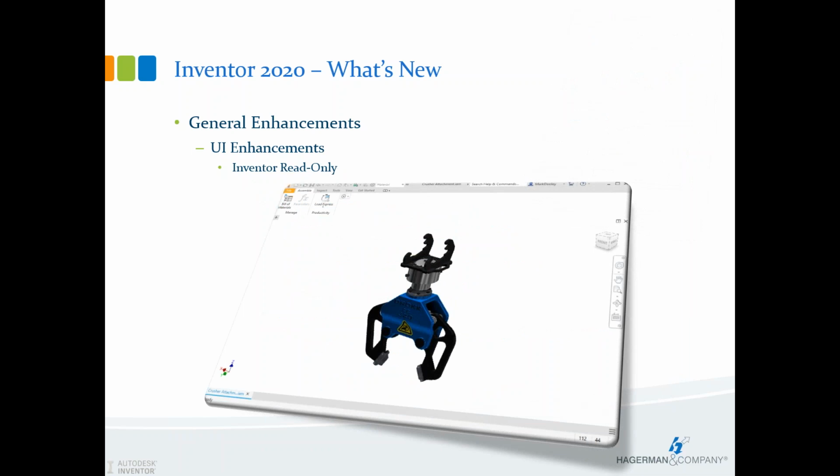So the Inventor read-only, and this is big for some users because it doesn't require a license to view the model. And so this installs directly with Inventor 2020. Once you activate Inventor 2020, you have the Inventor read-only option available in the Start menu, All Programs, Autodesk, Inventor 2020, and it'll say Inventor read-only. You can put a shortcut on the desktop and launch it. It doesn't consume a license. You can open any presentation file, drawing file, assembly file, or model file.